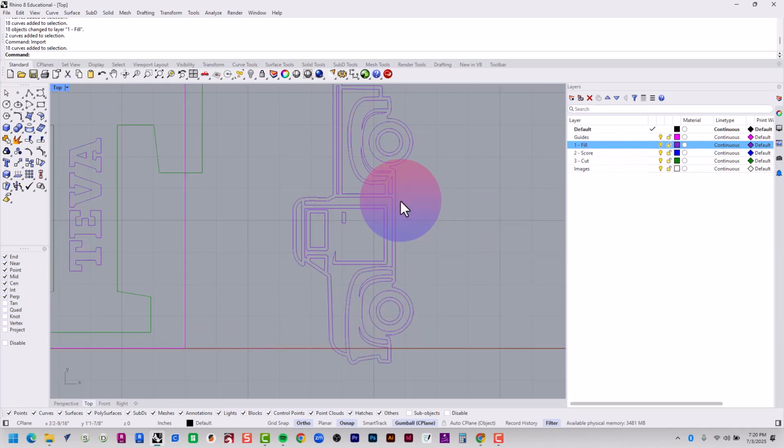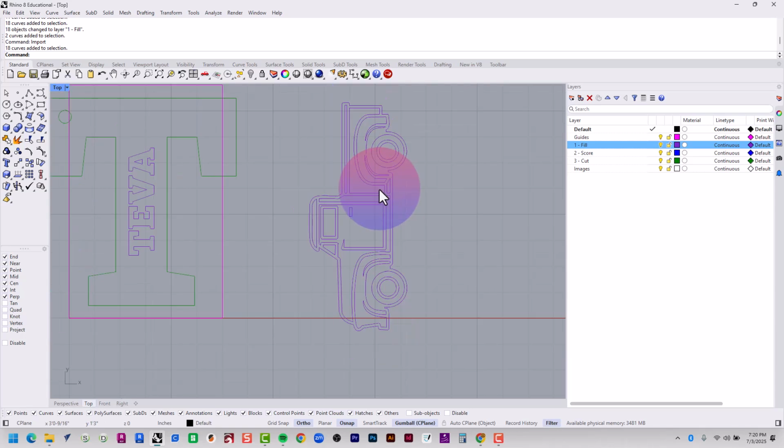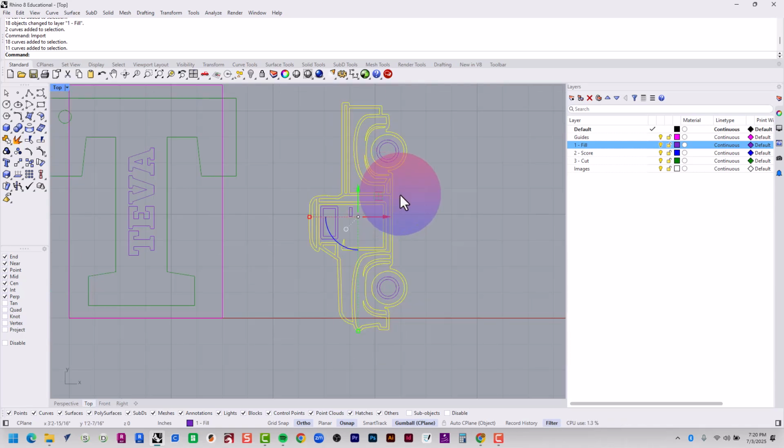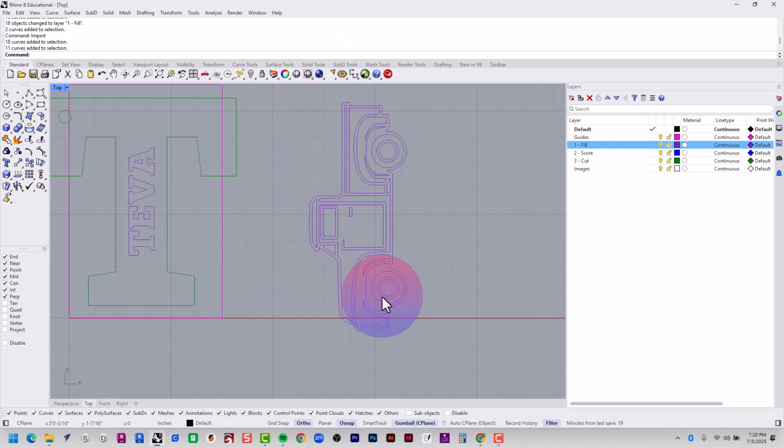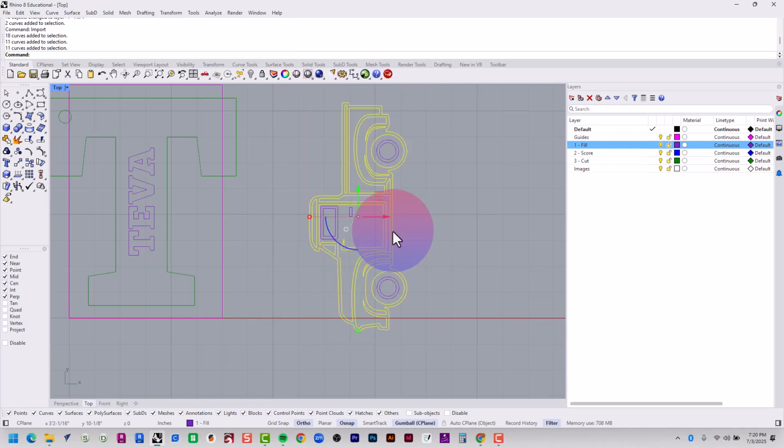And the next thing I want to do is create an offset line of the boundary of this that is a little bit offset, so that I can create a shape that will cut this thing out. To do that, I'm going to select these outermost curves and type in curve Boolean. What curve Boolean does is it allows you to take all of these curves and create a closed curve based off of either inside regions that I want to keep or the entire outside regions.